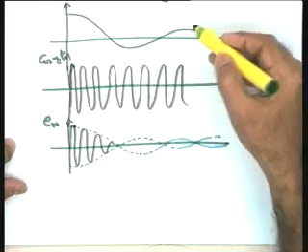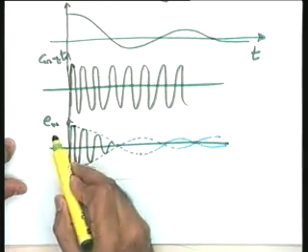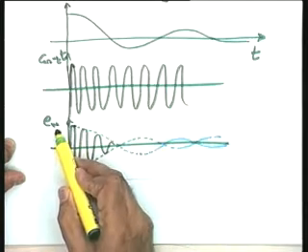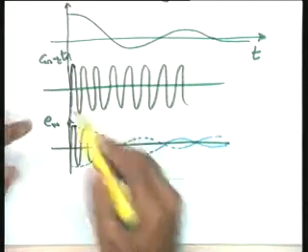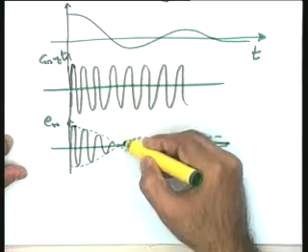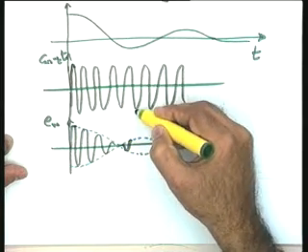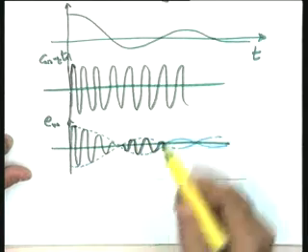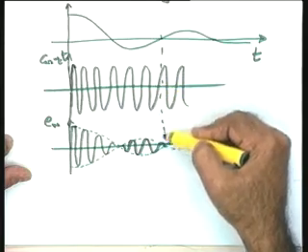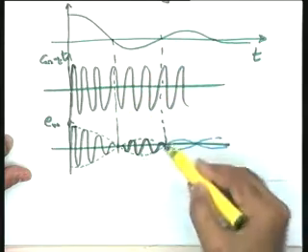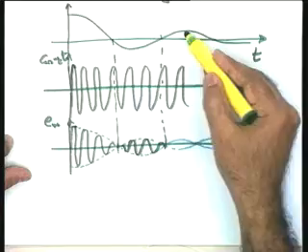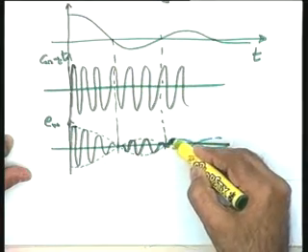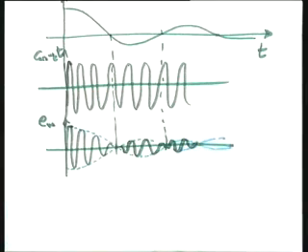Now when the sign of EC changes, in that particular case the phase reversal will take place. So in this part of the curve, EM should be anti-phase to cos omega ct. Let me show it this way. This is the maxima, so let me show it just opposite. This is the minima, so here is the maxima, and so on. So now again the phase reversal is taking place at this particular point. In this case again EC becomes positive, and hence EM will be in phase with the carrier. Drawing a suitable curve is your responsibility.